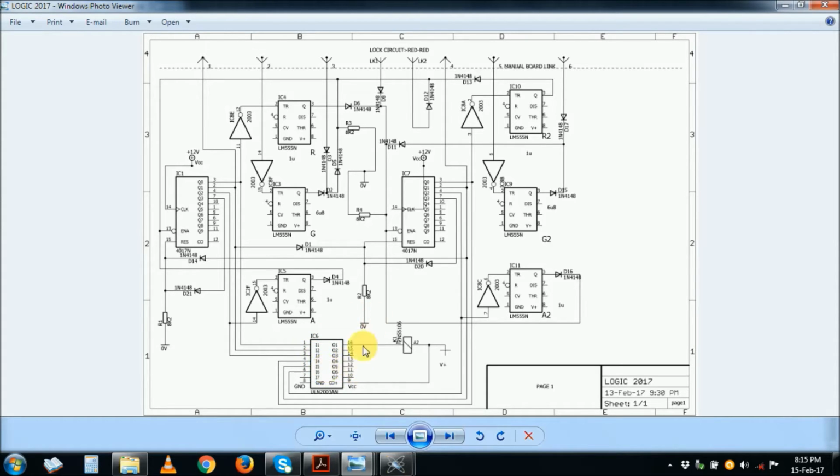You connect your relays here, and the relays can be 12 volt, can be 5 volt, depending on the relays that you get. Otherwise, you get the relays that will actually be working DC. They must be DC. I actually recommend that you use 12 volt for the control. You can use 24 volt if you get 24 volt relay. You can put your 24 volt here, but separate it from the power of the control circuit. So this is the nice thing about these relay drivers. You use different voltages. The relays will actually come in because this just goes low and operates a relay.